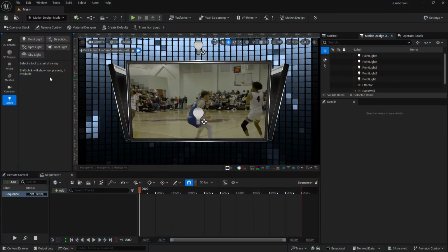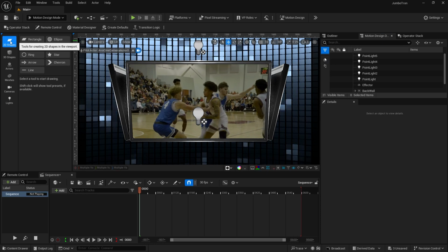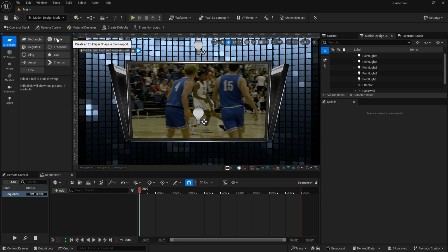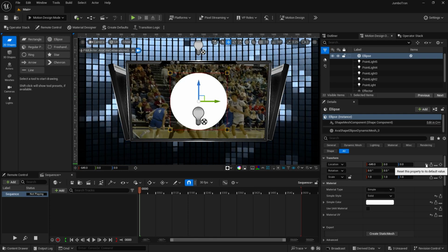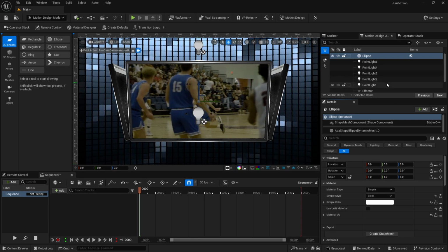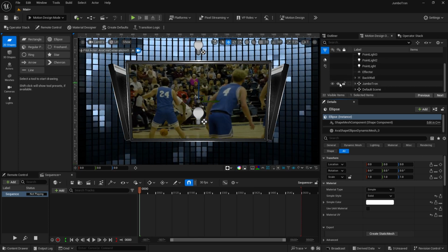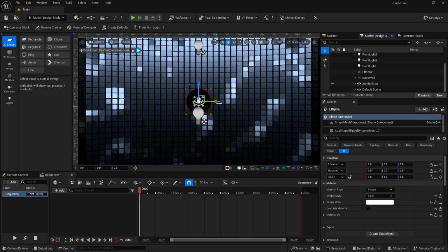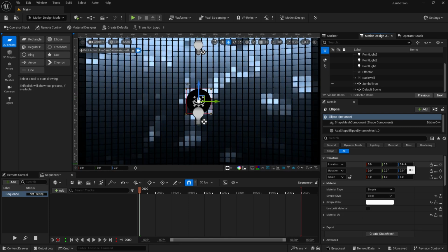To create those rings, I'm going to use 2D shapes. And so I'm going to go into the 2D shape tab there, select the ellipse. I'm going to add the first one in, just double click on that. There's our first ellipse. Let's reset that location right there so that we can see this a little bit better. I'm going to hide the entire Jumbotron. I'm going to scroll to that Jumbotron null right there and just click the eyeball so that we can hide it.